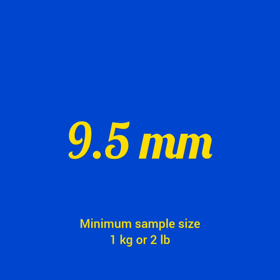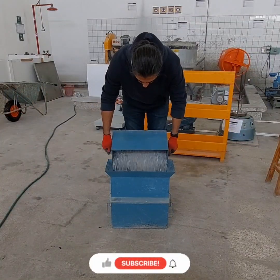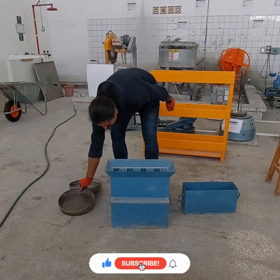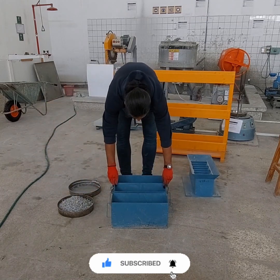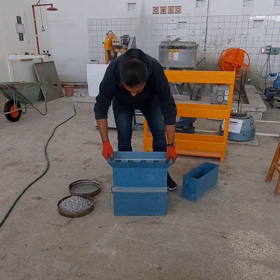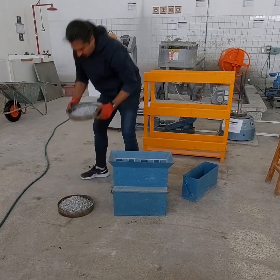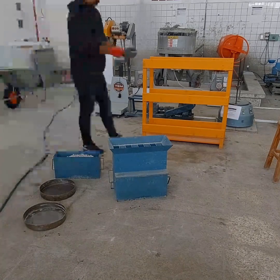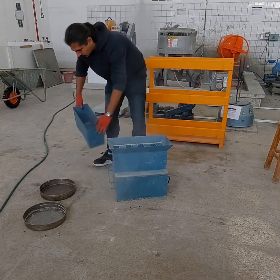The next step in the process is sampling. The amount of sample you'll need should be more than 4 times the specified amount shown in the previous picture. For example, for 9.5, 12.5, and 19 mm aggregates, you'll need to take more than 4, 8, and 20 kilograms respectively. Once you've collected the sample, you'll need to reduce it to the amount suitable for testing. It's important to note that the test sample should be approximately the quantity desired when it's dry.